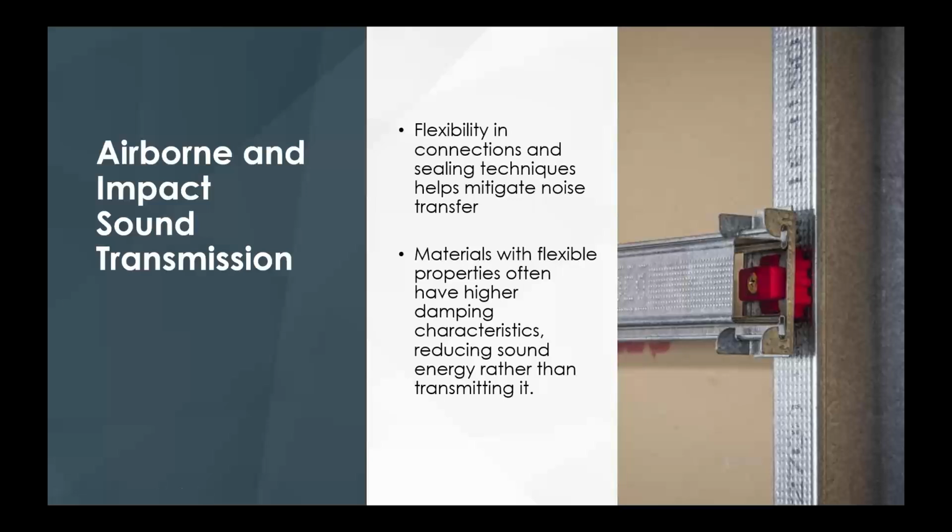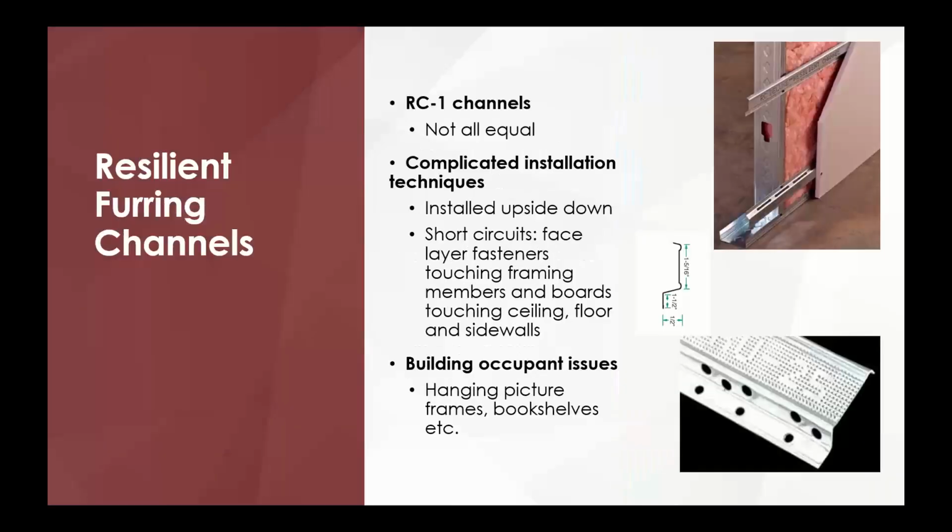Whenever you can get more flexible properties, it's going to have higher dampening characteristics, and it's going to reduce sound energy instead of transmitting it. So that's another way that you could do that. The same thing with resilient channel.